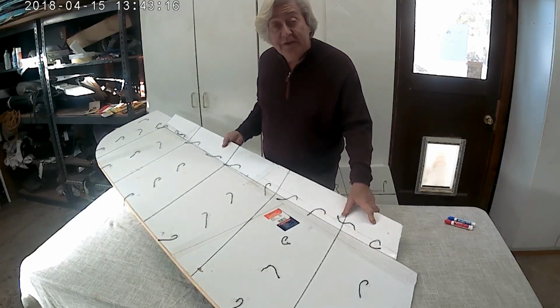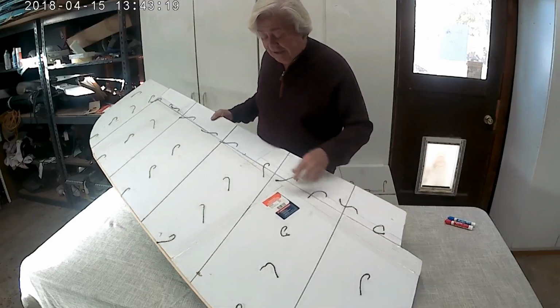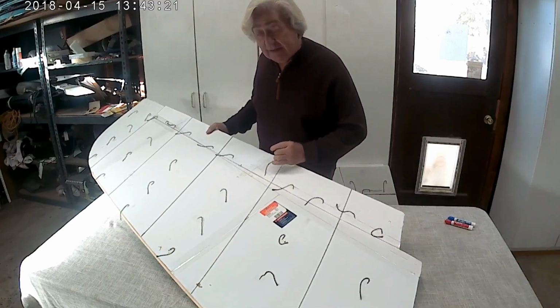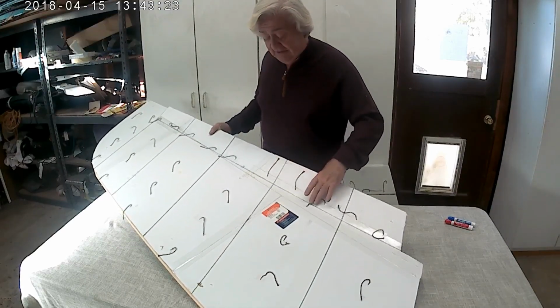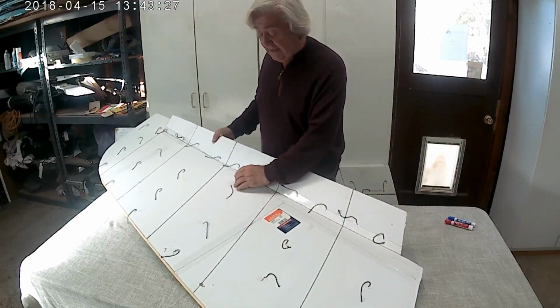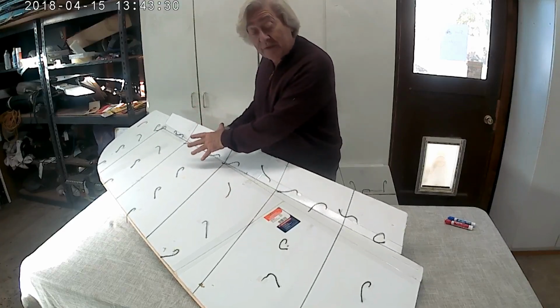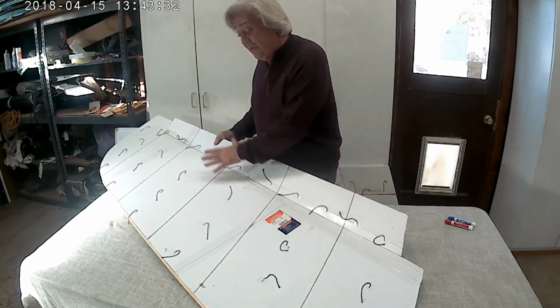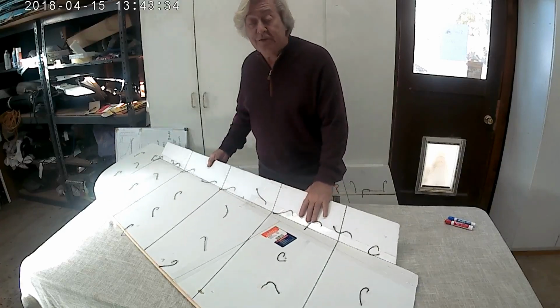And you might be flying just fine, flow's attached. You know, these guys are going straight back like this, everything's cool, right? And then you deflect it a little bit more up and out they go this way. These guys start to follow it, and before you know it, you got a whole bunch of span-wise flow, put some shear into the boundary layer, and you get premature stall.